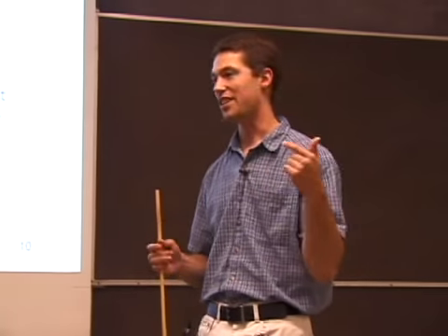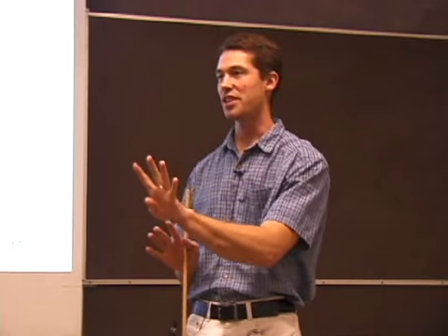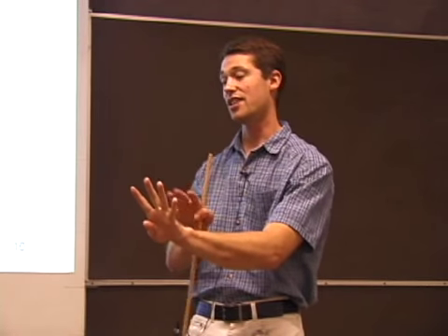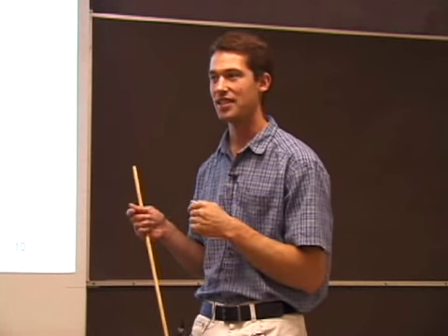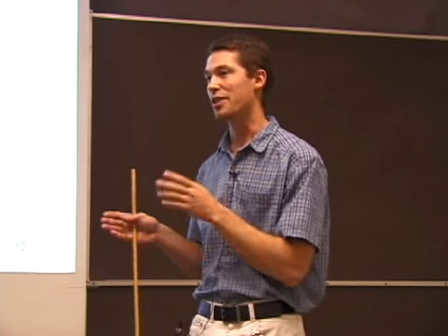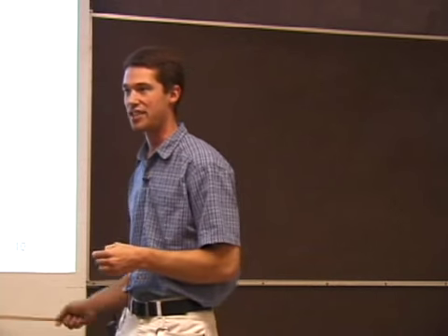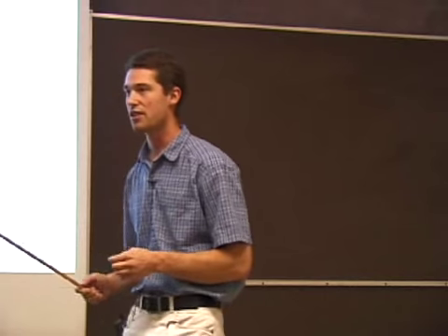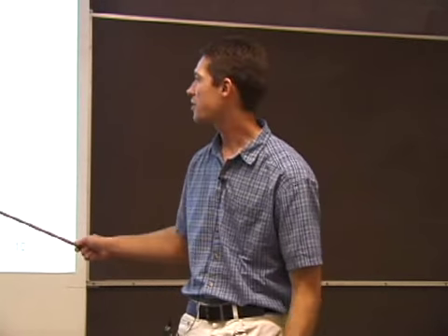Essentially what happens there is when you tell it, I want you to put out some voltage, it has some bits that represent the previous voltage, and it has the new ones, and it just sort of randomly flips them. So when you go from -1 to 0, you have to flip all of the bits. And what that means is you get sort of random outputs on the way through. This causes a zero crossing glitch, and it's the main noise contributor for, I think, the whole output chain. That's really the largest fraction of noise.